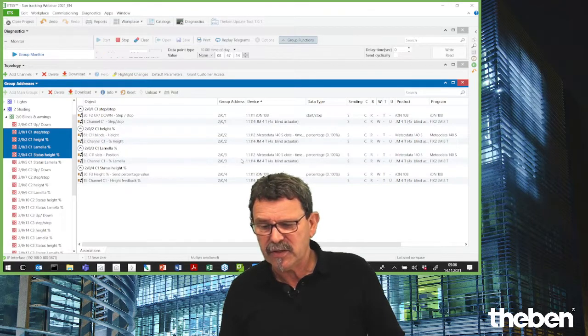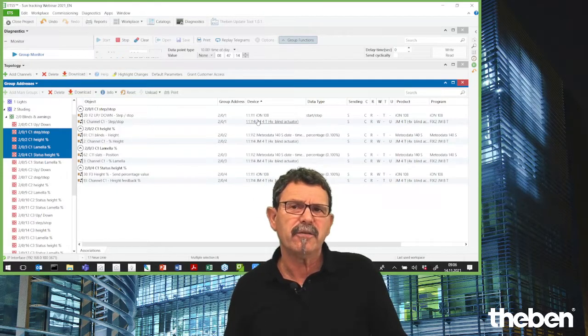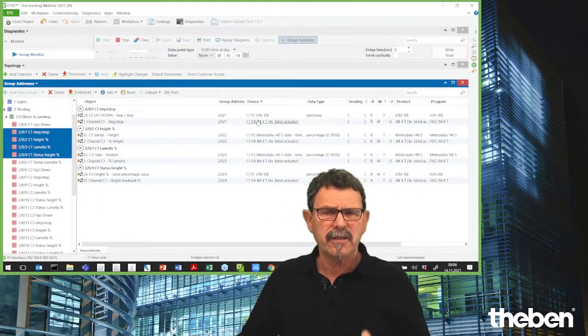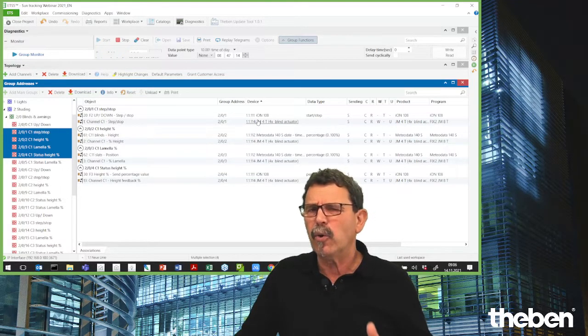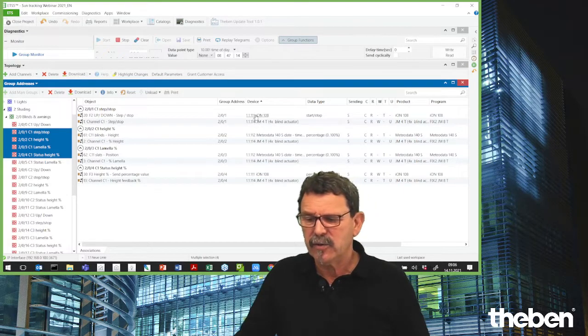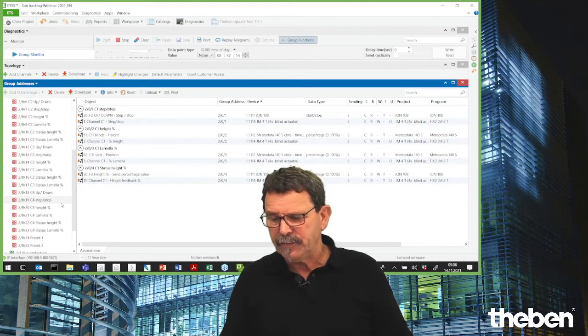The weather station is sending that. Here we need the communication to the shutters and blinds actuator. We need the height coming from the weather station, and we need the reasonable height received from the actuator, and we need manual operation. I think nobody will accept that you do have a totally fully automated solution. So in all the buildings, even private solutions, or if it is a public building or school, there is always a demand to operate manually, and due to that you definitely have to give an up and a down to the reasonable shutters and blinds control.